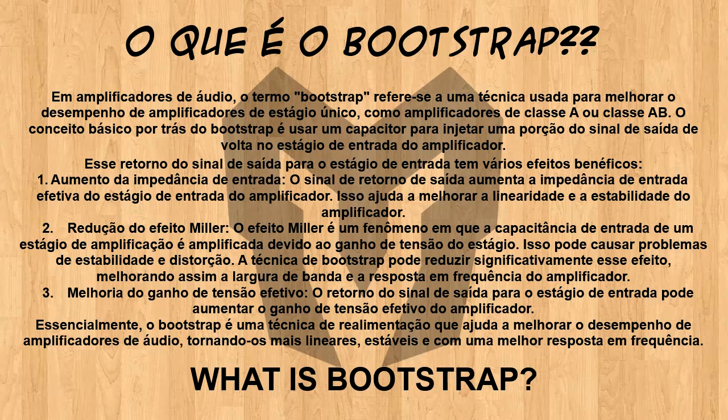What does Bootstrap mean in audio amplifiers? In audio amplifiers, the term Bootstrap refers to a technique used to improve the performance of single-stage amplifiers, such as Class A or Class AB amplifiers. The basic concept behind bootstrapping is to use a capacitor to inject a portion of the output signal back into the amplifier input stage. This feedback of the output signal to the input stage has several beneficial effects. 1. Increasing input impedance. The output feedback signal increases the effective input impedance of the amplifier input stage. This helps improve the linearity and stability of the amplifier.